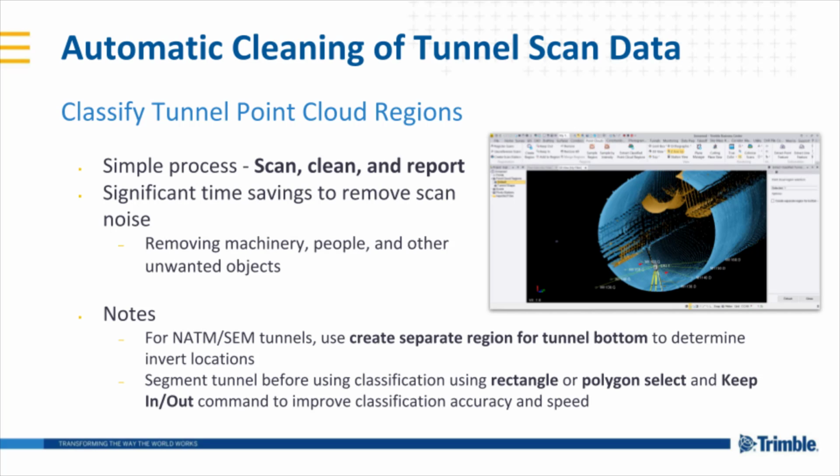Previous tutorial video on the new Classify Tunnel Point Cloud Regions command in TBC Tunneling module version 5.4. This is a useful command to automatically clean tunnel scan datasets. It's a simple process where you scan the data in the field, clean it in Trimble Business Center, and then report in the necessary format. This results in significant time savings to remove scan noise, such as unwanted machinery, people, and other objects.